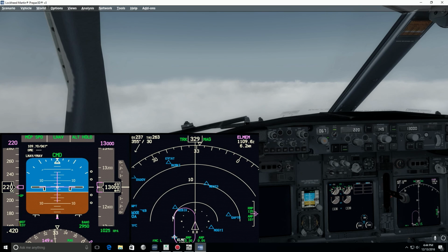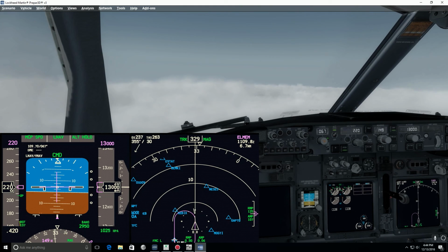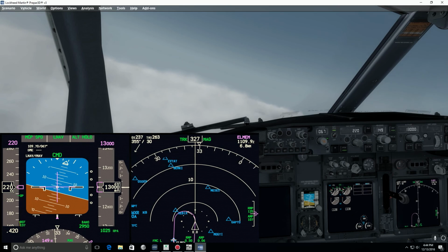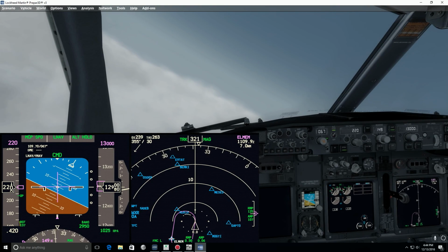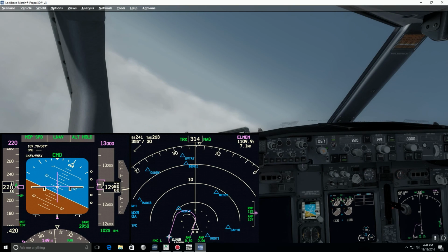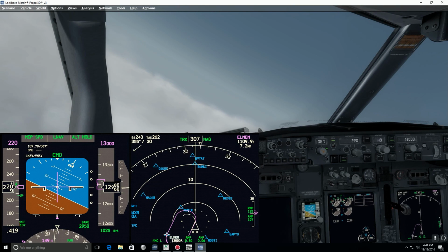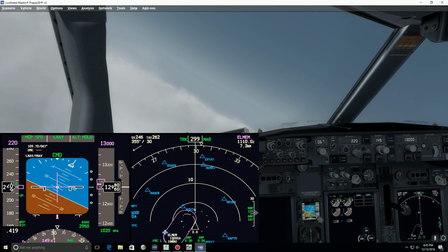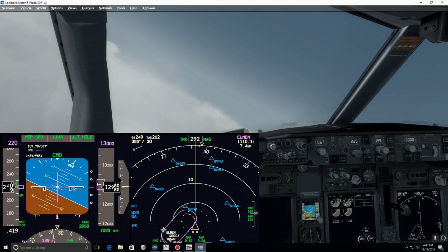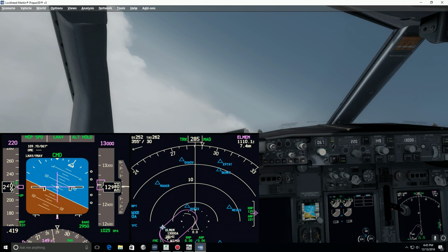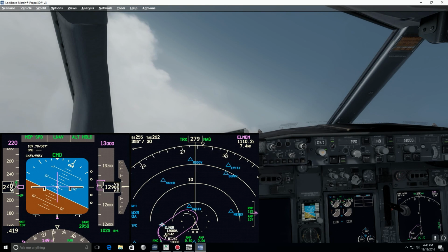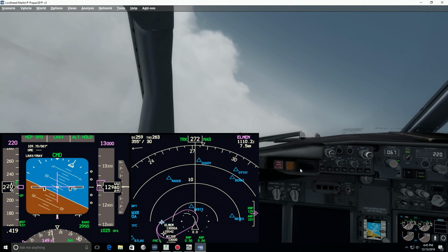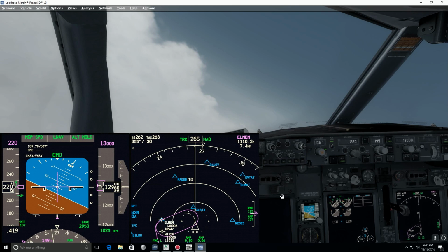Once the aircraft has turned inbound, we will exit the hold, and normally we should be able to start our approach automatically from overhead LMM going to Whiskey India 750. Okay, we are turning inbound, maintaining 13,000 feet. The local QNH is confirmed at 1025. No cautions. At this time we will do the descent checklist.